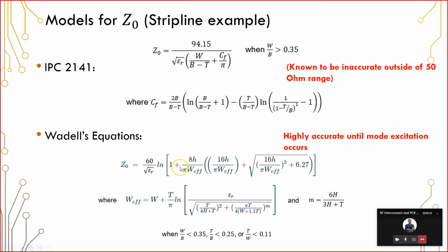Waddell's equations are also highly accurate, and they are also much more detailed, but you can use them to get accurate results outside of this 50 ohm range, just like we had for microstrips.